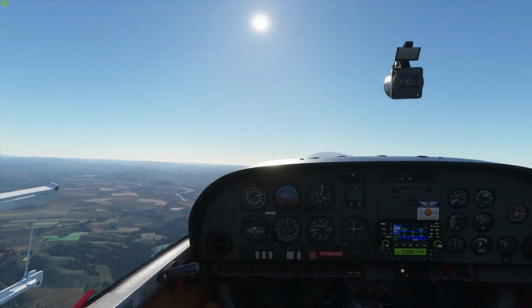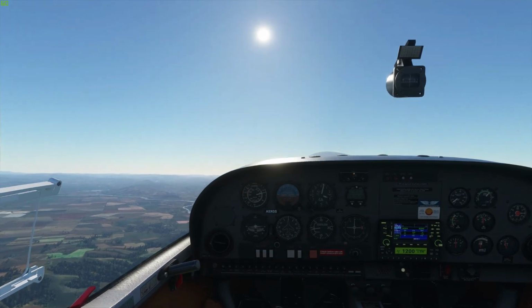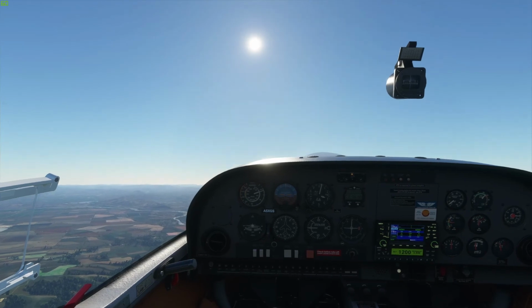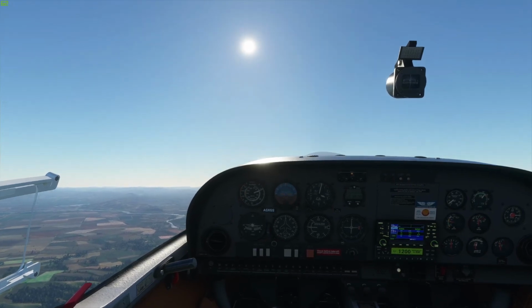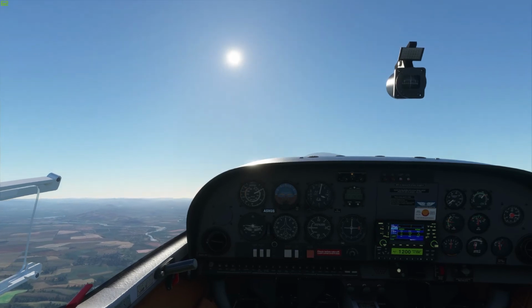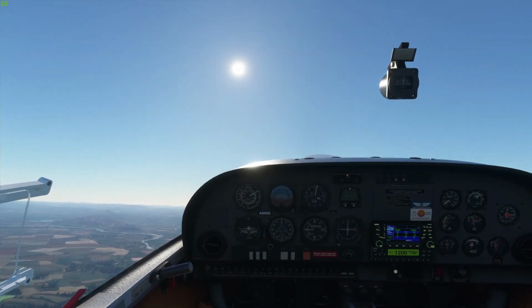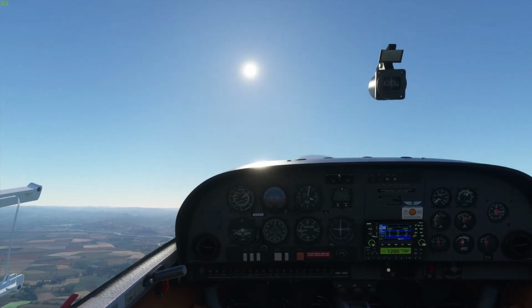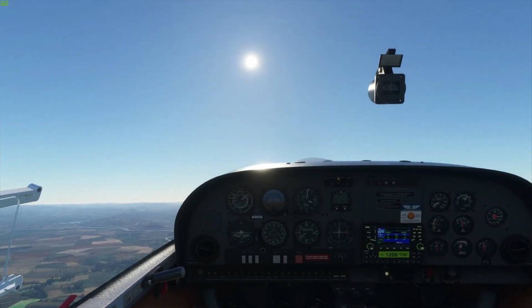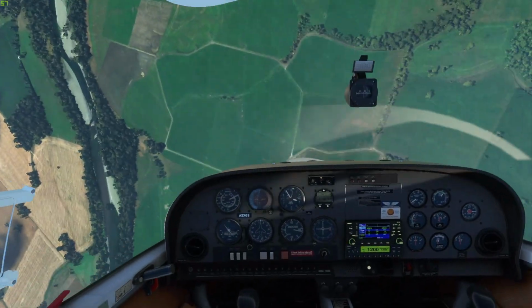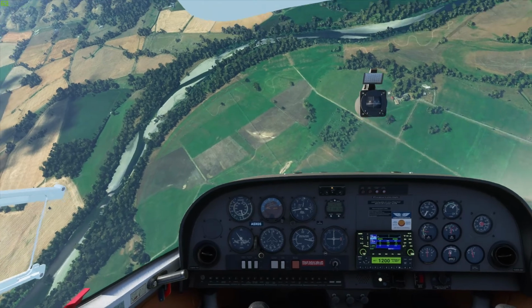Okay, there's a stall warning. So we do expect to get a wing drop on this one, probably to the left. That's what it did before. So there's a very high nose attitude. Well below the stall speed. And you can see the sink rate, so okay, she went right. Alright, that's a pretty aggressive stall. Just close the throttle.